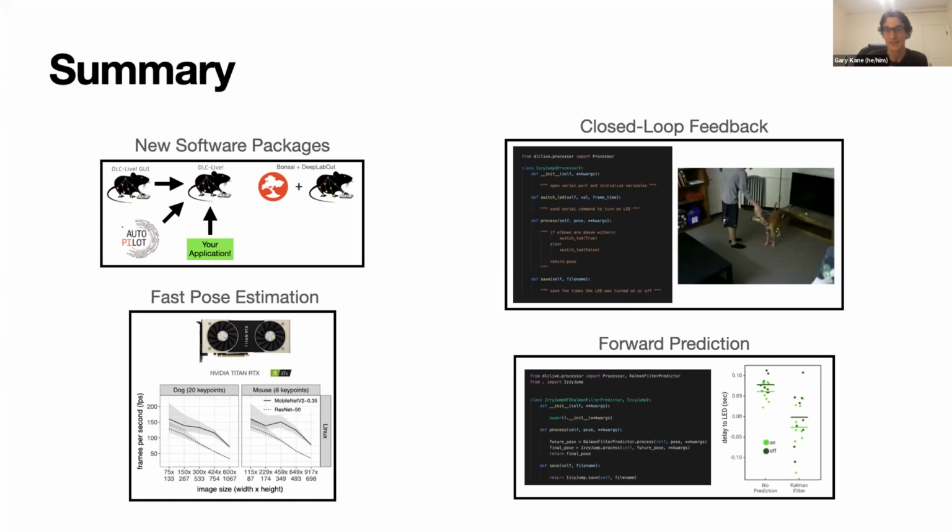So if the actual position of the limb has stayed the same, but because of just random noise, it thinks that it moved down quite a bit, then when you make your forward prediction, that noise is going to dominate the prediction, because the model is now going to think that its velocity is moving downward, but it's really staying the same. And so what the Kalman filter does is a technique for real-time Bayesian filtering. It uses the expected uncertainty, or some level of noise that it expects in these measurements, to get a better estimate of position, velocity, and acceleration, and therefore giving you a better prediction.